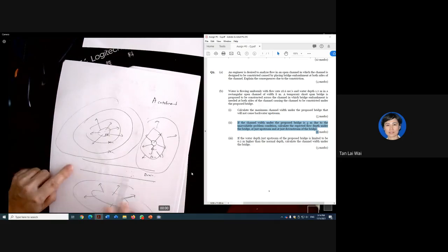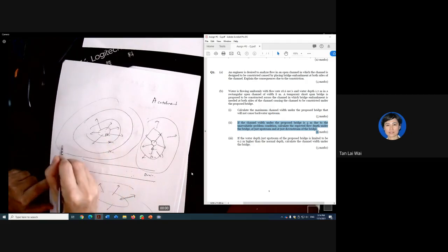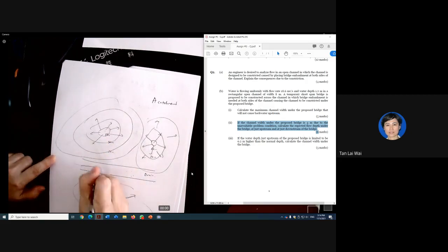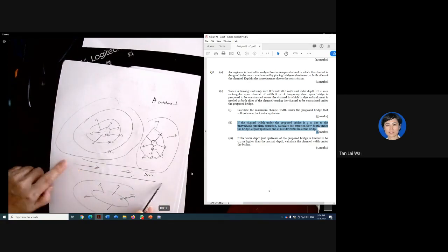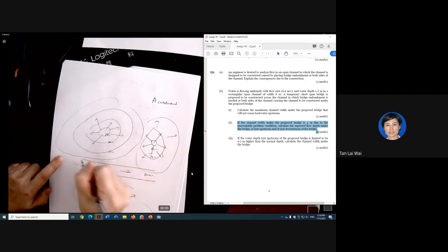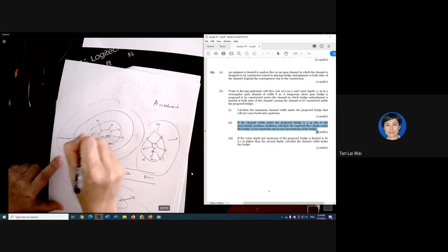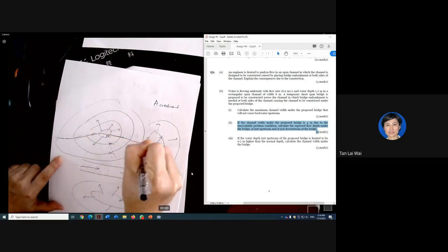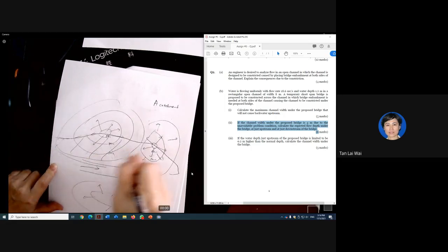So how are you going to estimate the area? Imagine that this is going to, at the end, fall into here. That's why you are going to determine the slope of the drain. See which direction it flows to. So this will go into here. So you can draw something like that to get this would be your area.